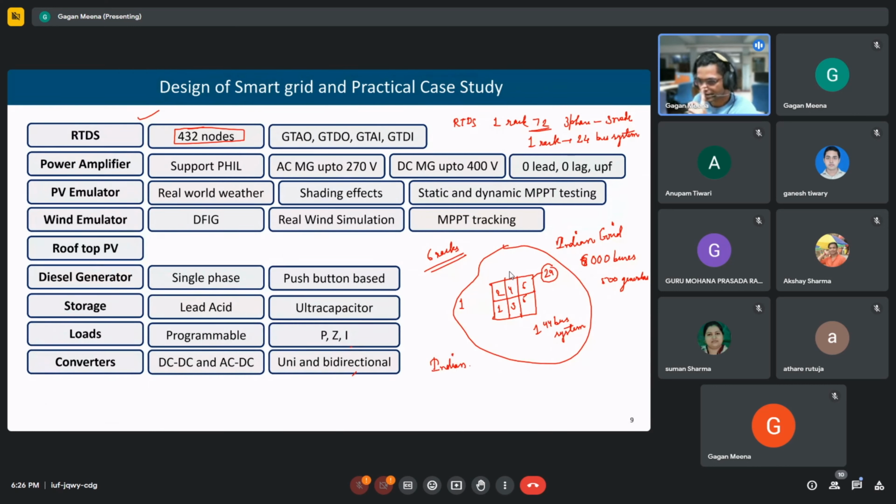which has more than 6,000 buses, this transmission network was reduced. So we get a reduced transmission line model. We can use reduction. There are certain reduction algorithms which combine certain nodes into a single node. They aggregate all the generators and loads at that single node. So, let's say, some districts will be clubbed together as one node. It all depends upon the topology of the network. The topology of the network is taken into account while doing this reduction of the network.